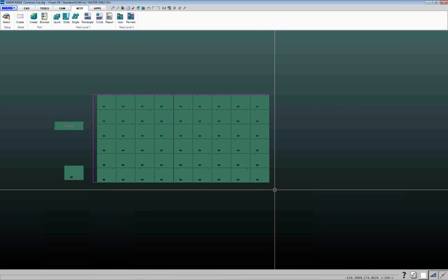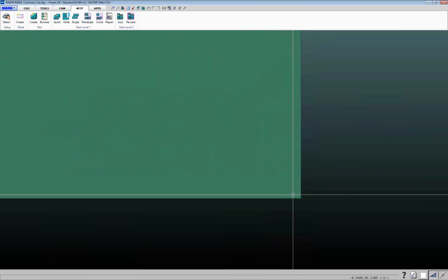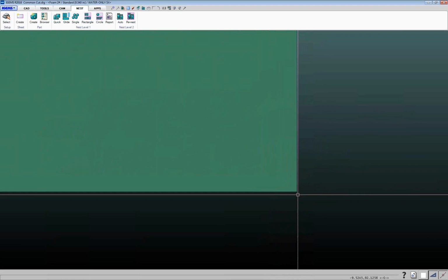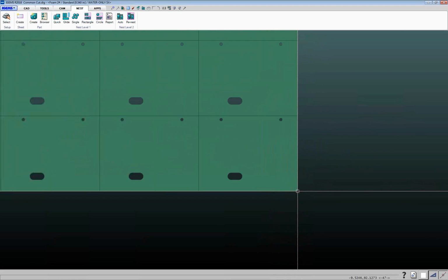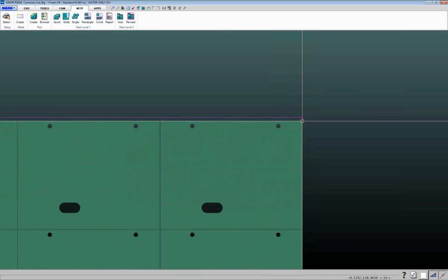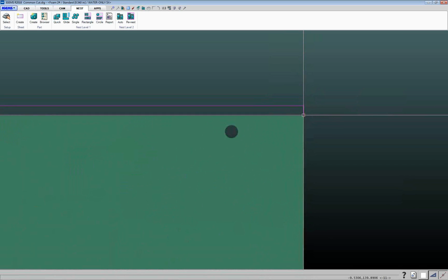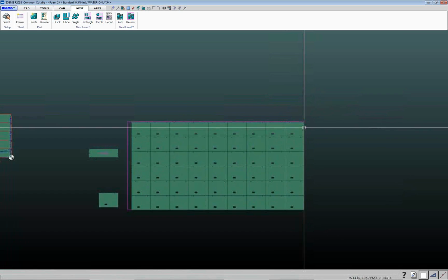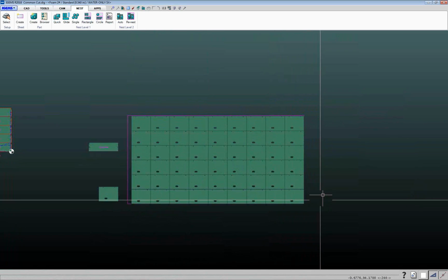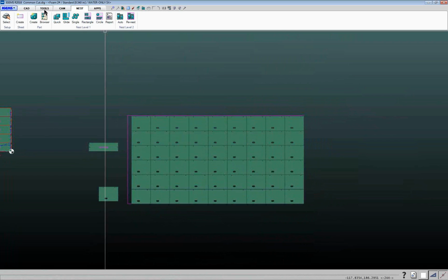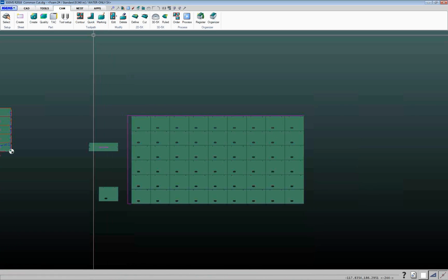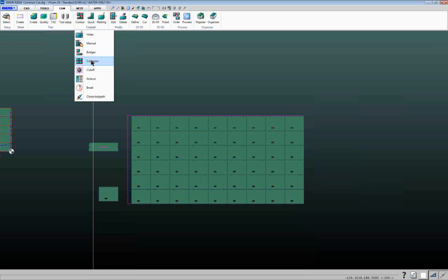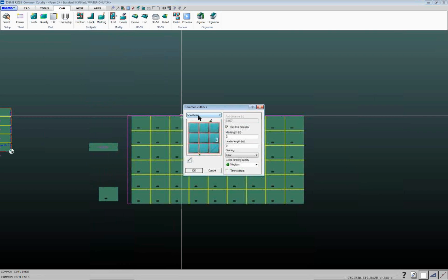And if I go back to my common cutting, what I'm going to do on this one is the trim to sheet option. So I've set my sheet border to 0, so it's put those parts right up against the edge of the sheet. So as long as I can accurately position the sheet on the table with a fixture, or my tolerances are loose enough that it'll allow, I can come in here, and when I do the common, I'm doing my sheet-wise.